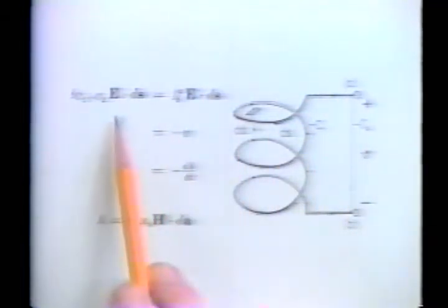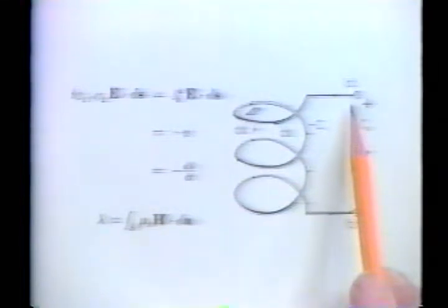Faraday's law then requires that this negative of the terminal voltage just equal the negative of the time rate of magnetic flux lambda through the surface. The surface S spans the entire closed contour. The surface S has as its edge the perfectly conducting coil along C1 and the contour C2 used to close the circuit in the region of the terminals. The surface S includes the sum of areas enclosed by each individual turn.